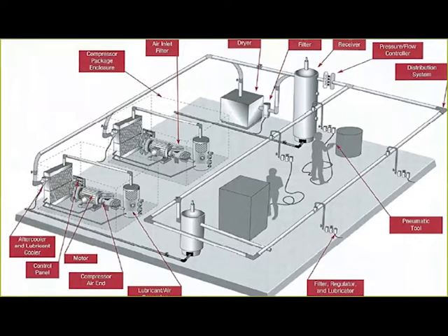An important first step in managing this cost is to understand just how much you are spending to supply compressed air. Periodically monitoring the compressor operating hours and duty cycle will provide the data you need to estimate your total consumption and the associated costs. You may be able to estimate your total leak loss by observing compressor operations during shutdown periods when you would not expect any demand for the compressed air. This provides a baseline to measure improvements in performance and savings.